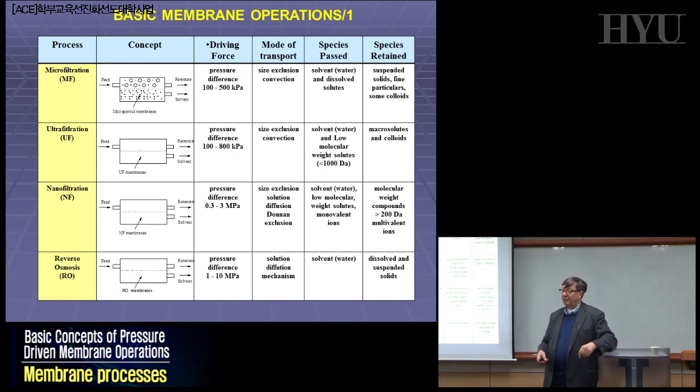And you can make a very nice show that, that is microfiltration, I know what it is. Because that is a standard system at the end of all the production lines, even if the operator doesn't know, because these systems are nice boxes, but inside there are membranes of this kind that just separate the species that can cause cloudiness or transformation over time. And so you have a very stable beverage that can stay in a bottle for 3, 4, 5 years. If you don't do this, after a few months, with changing temperature and more light coming in, you will see some cloudiness, the fluid is no longer transparent.